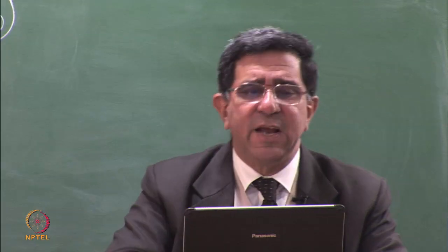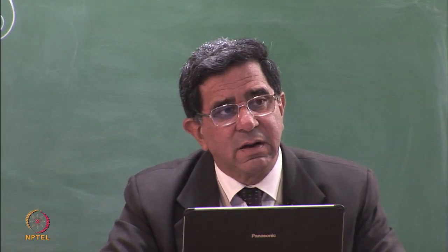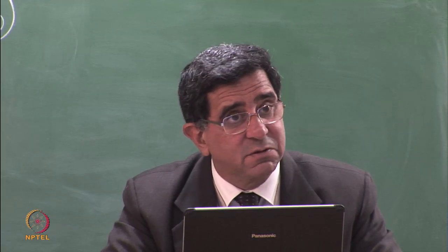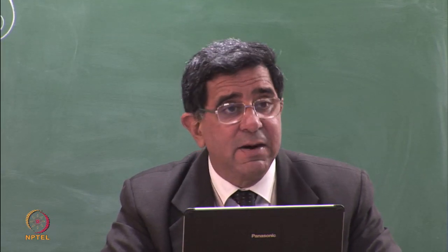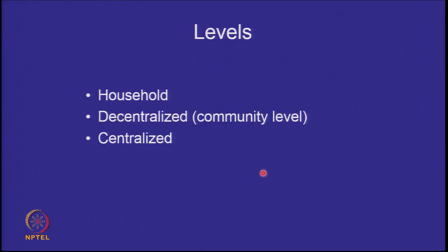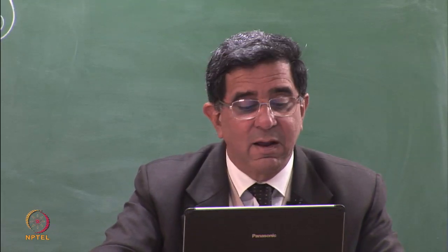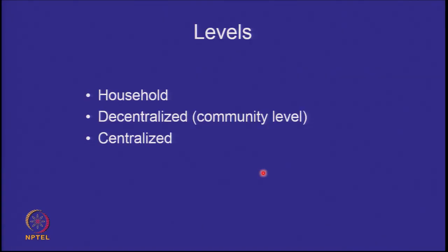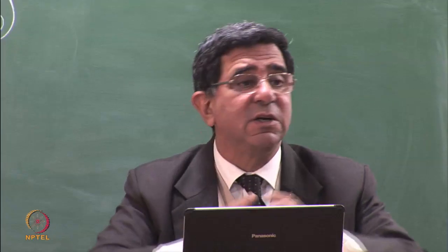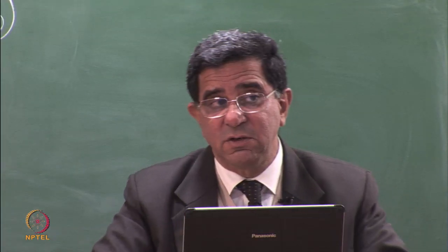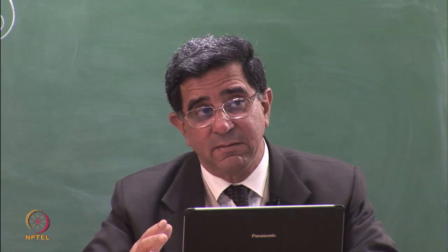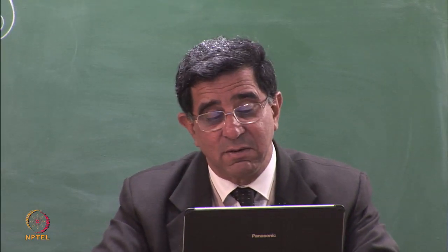So all that we are saying is that this integrated solid waste management is very important. It can be done at the household level, which is the best, but then you are dealing with tens of thousands of people and making them fall in line. It can be done at the community level. You may say, all right, I will not do so much at the household level. I would like to do composting at the community level or waste to energy of my society. I'll do biomethanization and take the methane out.